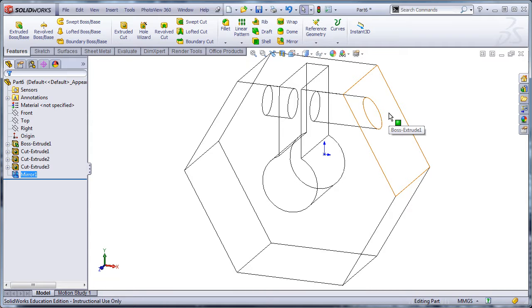So I want you to understand that while in the sketch or in AutoCAD, when you mirror something, it just duplicates the geometry on the other side. In 3D, if you've tied that geometry as a feature to some surface or a plane or something, all of the mirrored copies are going to connect to that plane or surface. It's not a geometry pattern. It's not a geometry thing, if you will. So we can't quite do that.